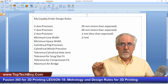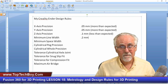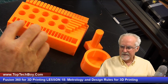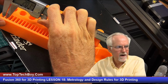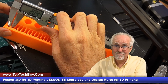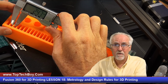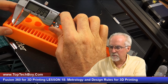Now, it's kind of interesting: the nozzle is 0.4 millimeters and I'm printing at 0.2 millimeters, so maybe a rough rule of thumb is that you can print to about half your nozzle width. But the other thing I'm interested in is how well am I defining things? I told this one I wanted it to be 2 millimeters. Let's see what I actually got. You can see that I wanted 2 and I got 2.01, 2.02. That's better than my x-axis tolerance. If I said my x-axis tolerance is 0.05 millimeters, well, yeah, it's that or better. This one I wanted to be 1.9 and it's 1.9.